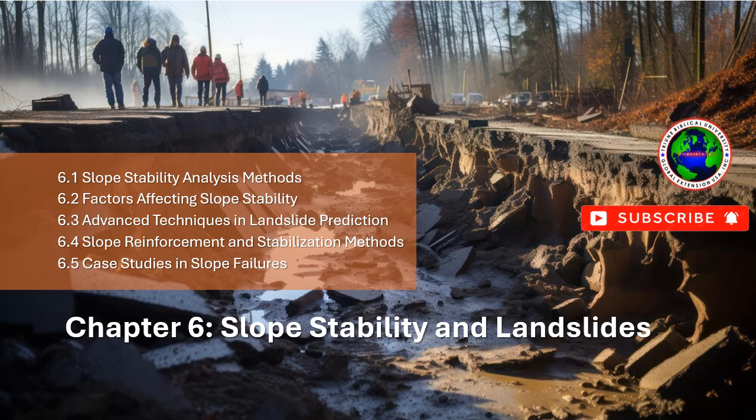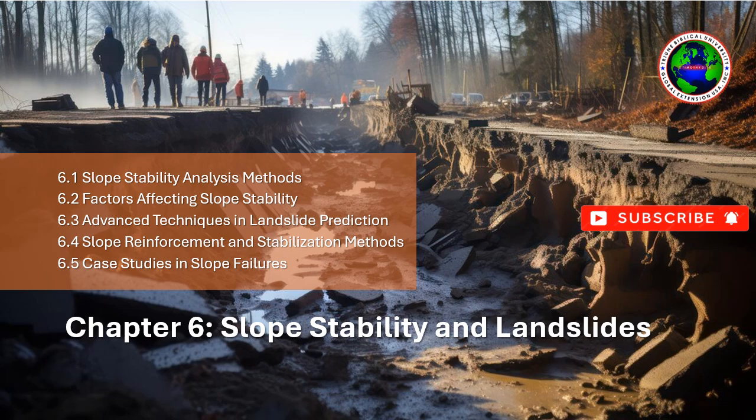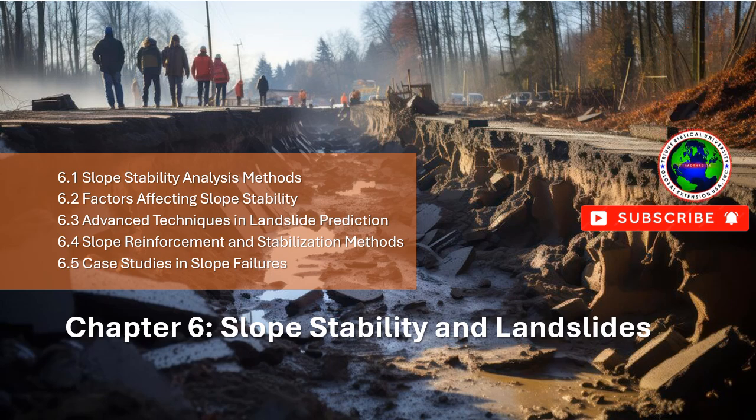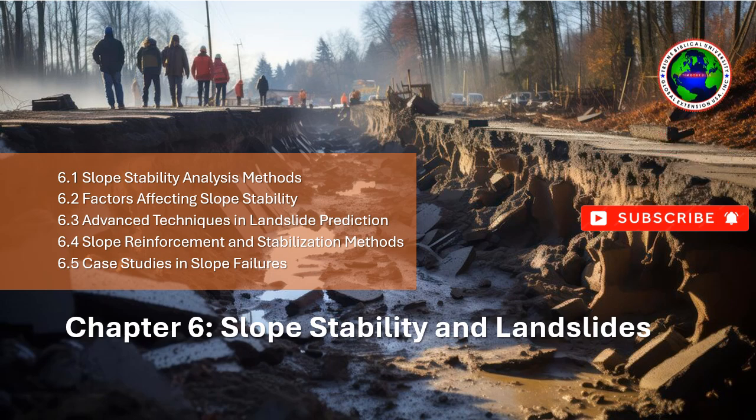Contributing factors: Heavy rainfall. Intense rainfall in the days preceding the failure saturated the waste heap, increasing its weight and causing it to become unstable. Improper heap construction. The slurry heap had been poorly constructed and was positioned on a slope above the village, with little consideration for its stability. Lack of drainage. There was insufficient drainage to control water infiltration, which increased the likelihood of failure.